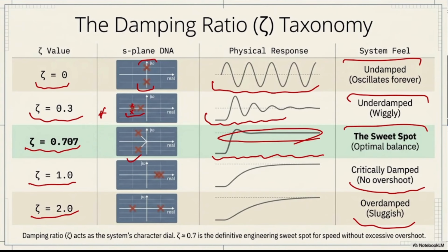Maybe you guys have a question at this point, saying, okay, you told us that our system is not going to be stable unless our poles are on the left side. But at this point, we can vividly see that I do have 2 poles on the right side, and at this point, I do have 1 pole on the right side. So in this case, I can say that since you don't have any imaginary part, you're not going to deal with any oscillation. So mostly your system is going to act as an exponential function. It means that those poles would try to reach the steady state. However, if you do have your poles on the right side, it doesn't necessarily mean that your steady state is something that you like.